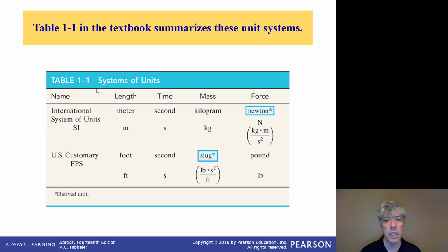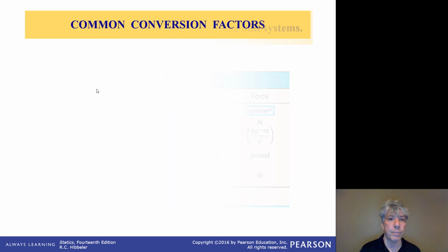Whereas a pound in English units, a pound force, if you want to figure out how many pounds mass it is, it's a little confusing. It turns out it's a one-to-one relationship, but that doesn't mean that 10 pounds mass will always weigh 10 pounds force unless you're on Earth. You might say, well, I'll always be on Earth. Well, maybe, yeah, that's true. But I want you to have an understanding of the difference between a mass and a force, okay, or a weight. They're very different things. A weight is just the effect of two bodies pulling on one another, where those two bodies have mass.